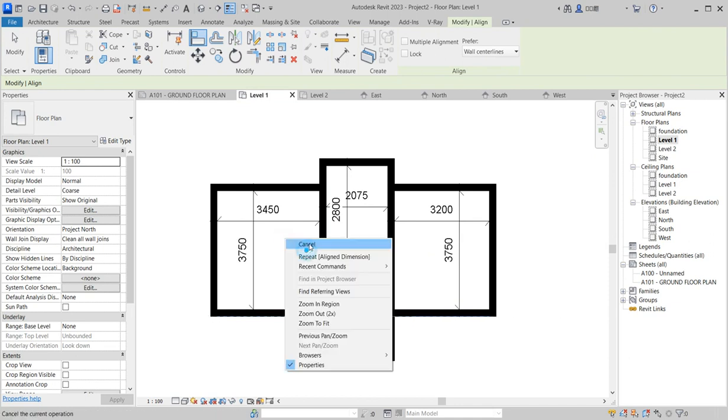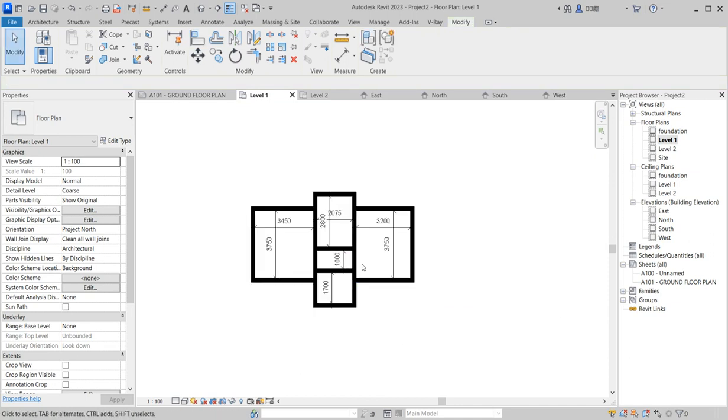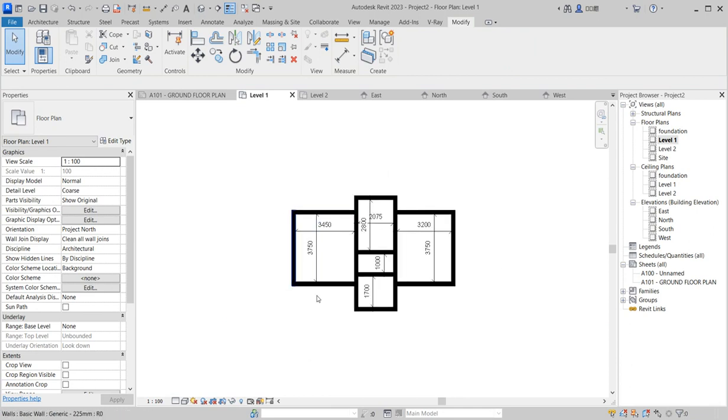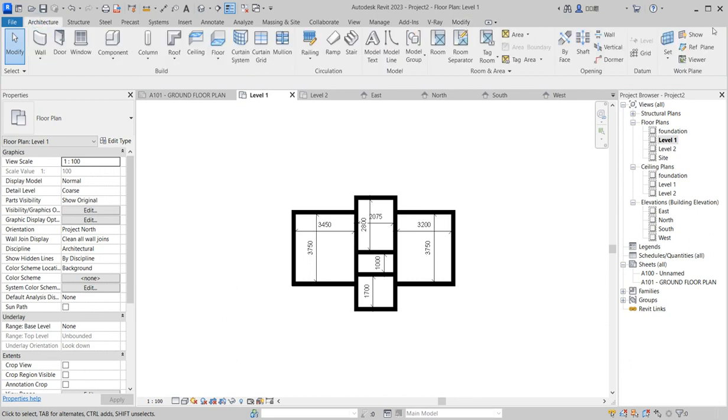Good. So they have the same something. So now if you have this in place, you can now get your grid and just have 2 grid here, 4 grid here. So let's go there and quickly create it. How do you create grid line? So you select grid architecture. At the architecture, you come to this and I say grid line.